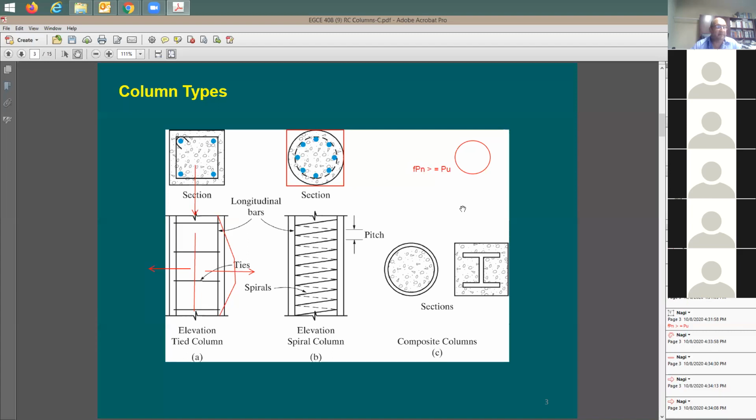We're going to say, well, I understand that the mode of failure is going to be opening right in the middle, like a vertical crack. I understand that. And having all of the spirals, all ties, is going to keep the concrete all together inside this shape. Therefore, this confinement provided by this tie is going to increase the strength of the concrete. You can see, yeah, this is true. Confinement here is going to be very critical.